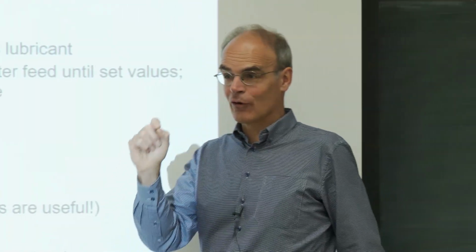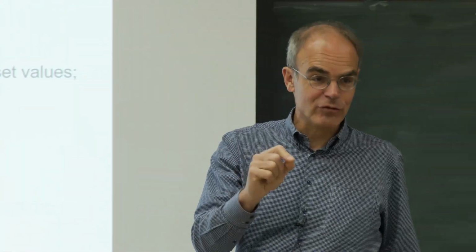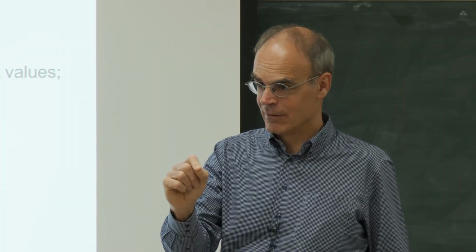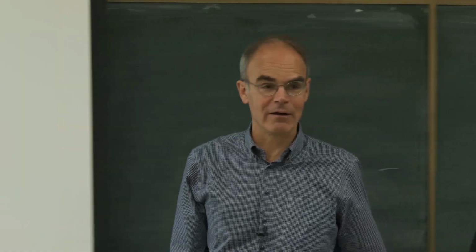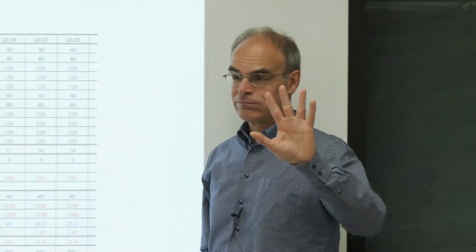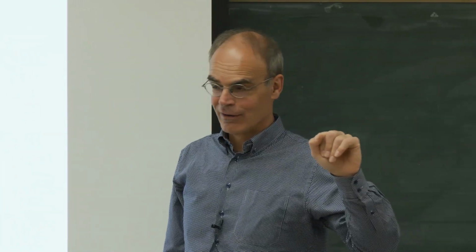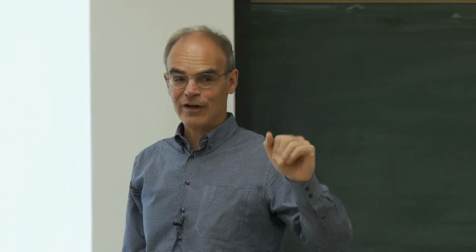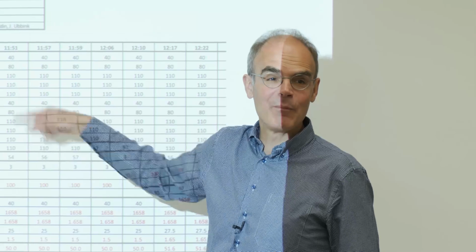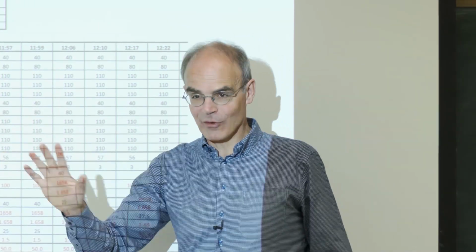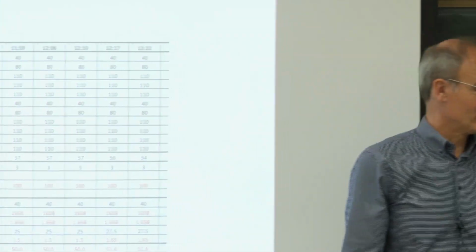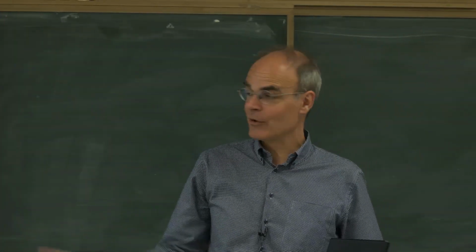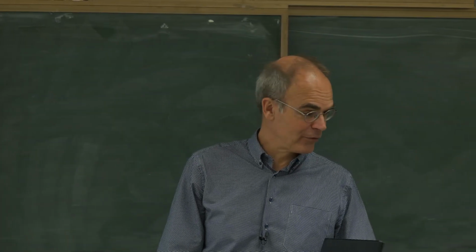Make sure that the internal clock of your extruder is set to the right time, because then you can correlate it back to that extrusion sheet and to the samples that you have. Because that 11:51 here, if your internal clock on your extruder is, let's say, 3:41 p.m., you can't link it back to your process data. So that's another reason actually to keep this sheet, but also make sure that the internal clock of your extruder is at the same time, because you can link everything back to your samples.